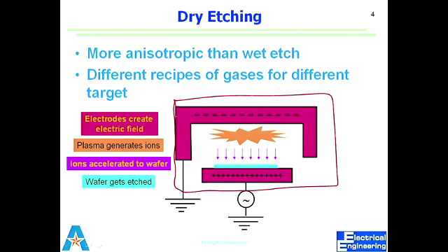Our recipe is designed in a way that we etch certain materials, but not something else. That is what we call selectivity. It may be the hard mask we are using, or maybe we may be using photoresist by itself, but selectivity is what will cause this reaction to be different at the surface of the wafer. That will result in different materials being etched at different rates.